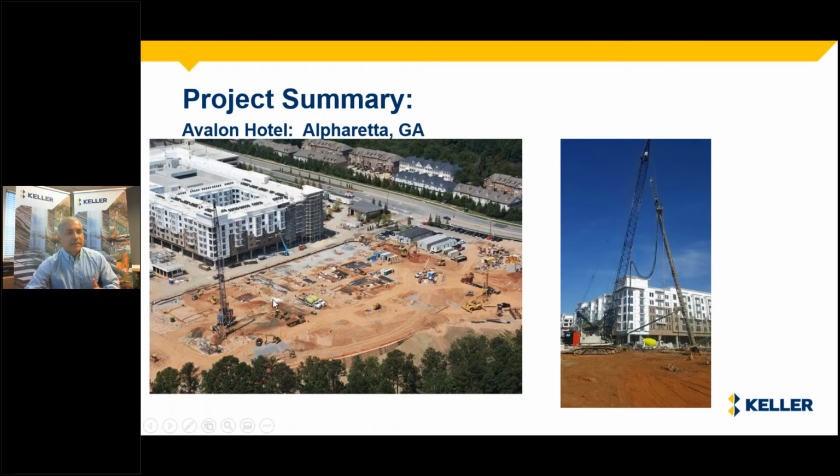It seems that my presentation missed a slide. On the slide that I'm missing, I had shown the use of strain gauges, as shown by the previous presenter. When we run the load test, those strain gauges graph out where the load and the friction are being dissipated in the soil, and verify that the pile's bottom two strain gauges were getting no load. So all the load was being held by the upper strain gauges, and therefore the pile was able to be shortened, getting some savings to the owner through a load test.